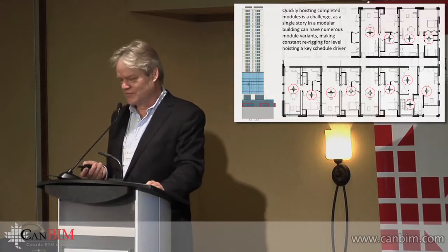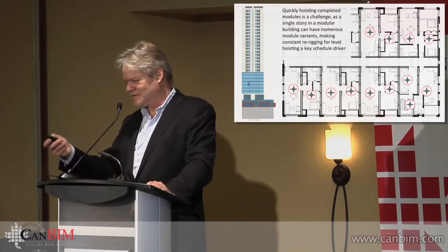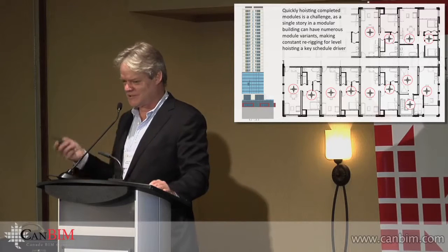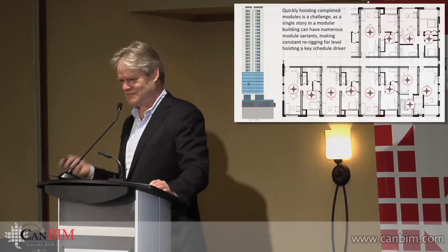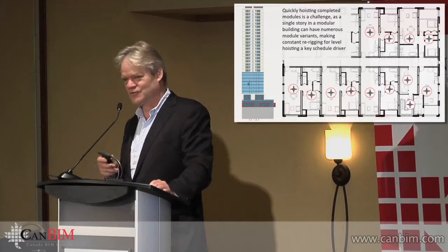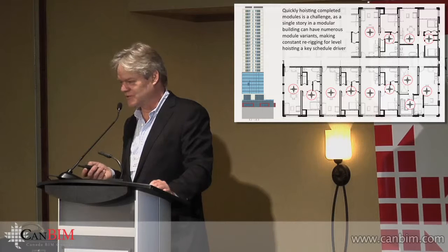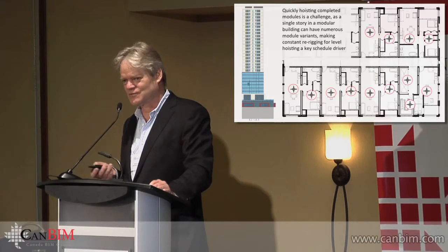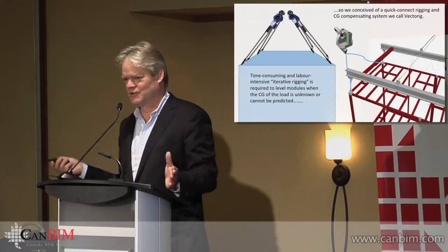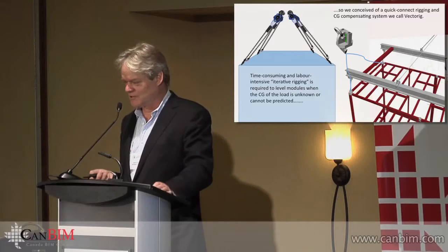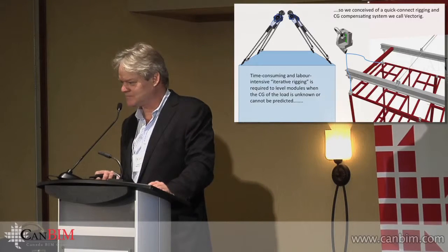So here's this issue of hoisting. The centers of gravity of these things flip all over the place, and you can't say, well, I'm only going to hoist the ones on Wednesday that have the center of gravity here, and then on Thursday I'll move the rig around and do it then. On any given floor, you are going to have a wide variety of centers of gravity, no matter what you do. The only building that wouldn't have this would be, I don't know, a military barracks or something like that. But any kind of attractive residential building is going to have this setup.